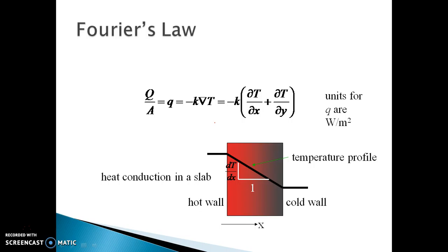If we try to understand the mathematics of this, or the dependable factors of this heat transfer, then Fourier first showed us the road; that is known as Fourier's law. This law tells us that heat flux, that is how much heat will be transferred per unit area per unit time from the hot body towards the cold body, is directly proportional to del T, the temperature difference across the wall, and this proportionality constant is K, the thermal conductivity.